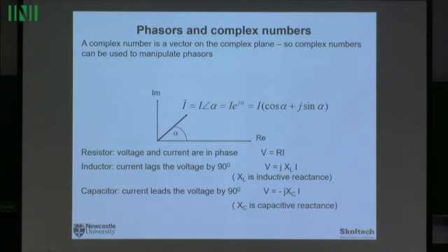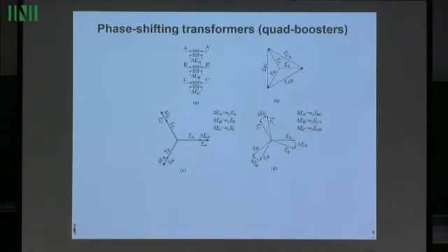So we can think about a transmission wire as being a resistor. That's the first order of approximation. Sorry, when people ask me questions, I tend to say this is farther down the line, in a few slides. But I'll go through modeling of the transmission line, because these are exactly relevant questions. So this is the first example of actually thinking about AC quantities as phasors. You remember I mentioned those phase shifting transformers, which I use to control the flow of power in the network, especially to repel the loop flows in Europe. So this is an example of how they work.